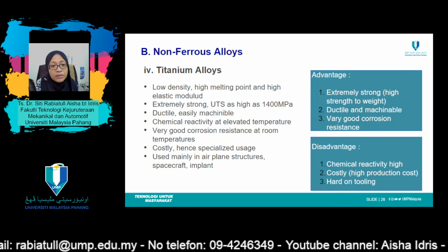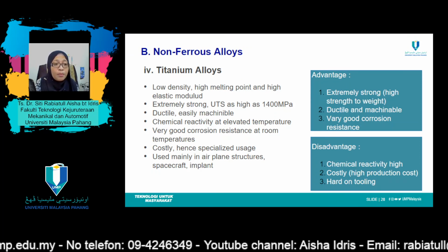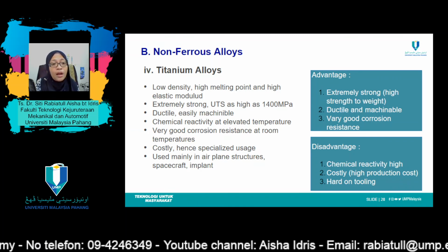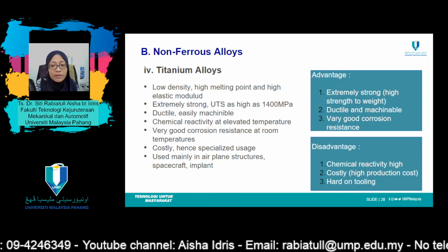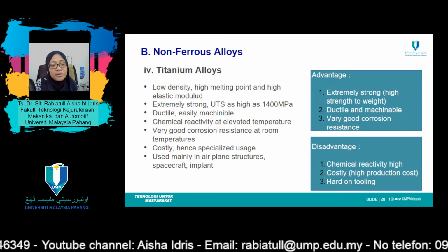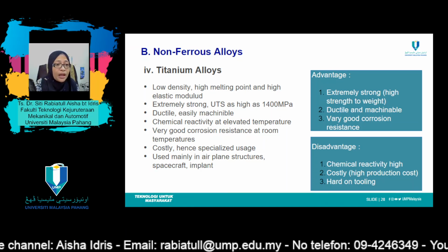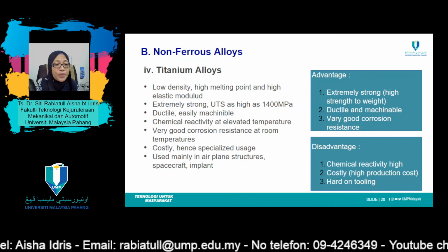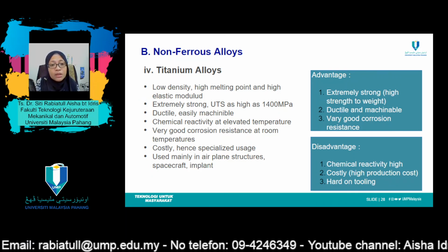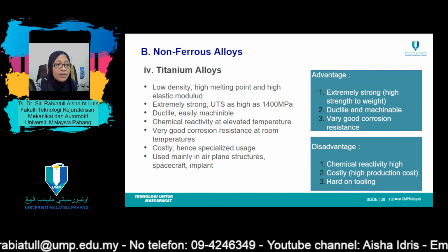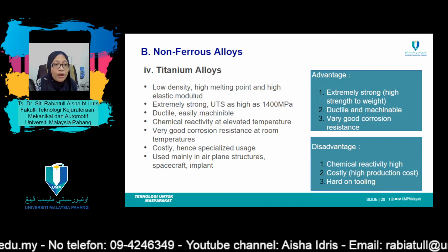They are attainable, yielding remarkably specific strengths. Furthermore, the alloys have high ductility and are easily forged and machined. The major limitation of titanium is its chemical reactivity with other materials at elevated temperature. This property has necessitated the development of non-conventional refining, melting, and casting techniques. Consequently, titanium alloys are quite expensive.